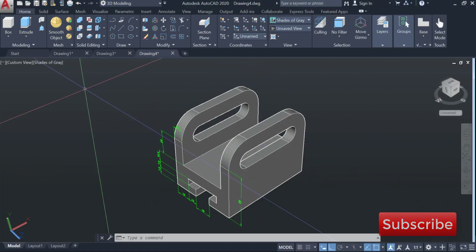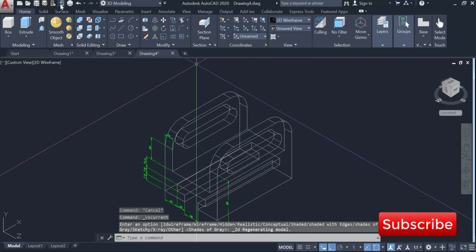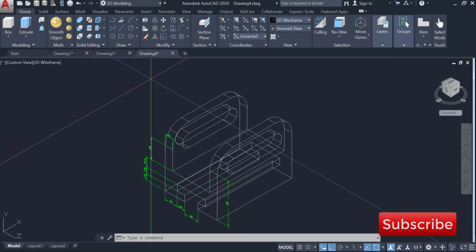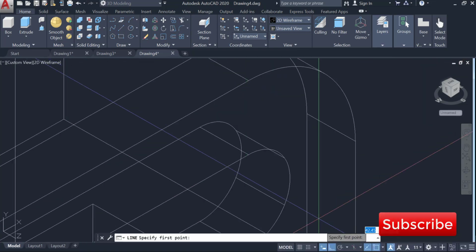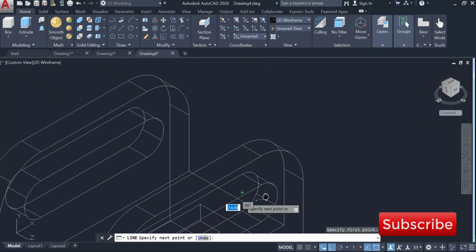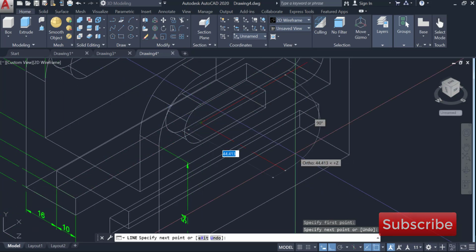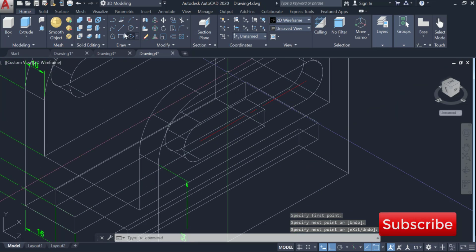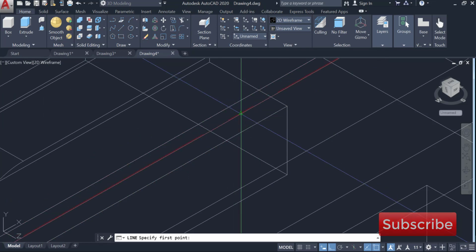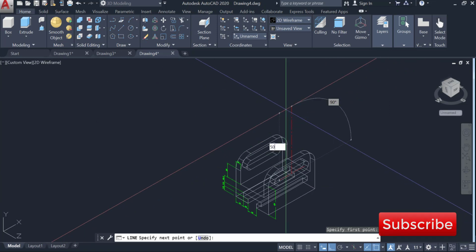So what we'll do, you have to switch it to extrude 2D wireframe. From here we need to switch to this line, center line. We need to draw a center line. You have to hover your mouse over this curve until this center point appears, and also hover your mouse over this curve until this center point appears. And now you need to draw our line of 50 units from the midpoint. This is the midpoint, so pull it vertical up and make it 50.